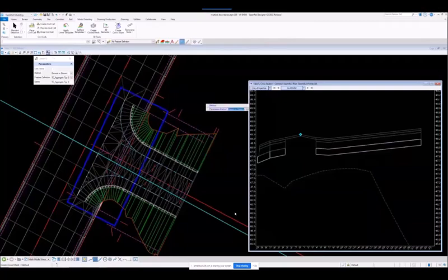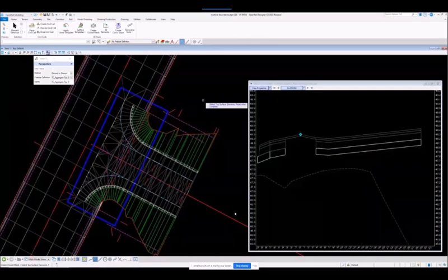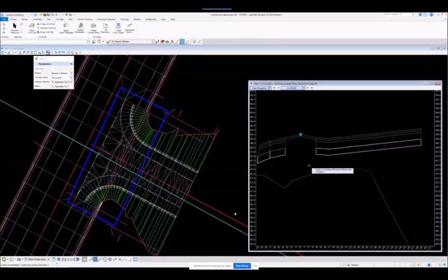So in this case, I'm just going to pick element to element, and I'm going to basically build from the bottom subgrade with these meshes here. In this case, it froze there a second. I'm going to pick the bottom mesh in cross section, which is nice because it's pretty hard to navigate that in a three-dimensional model. And it's going to say, hey, what side? I'm going to use the lowest side of that mesh because it knows it's closed when I selected it. And it's going to ask, okay, what's going to be your bottom side? Well, it's going to be my existing ground, also picked up in cross section. I can reset when I'm done. I can have multiple bottom elements, and it'll pick the lowest one of the two. In this case, I'm keeping it nice and simple, just picking one.